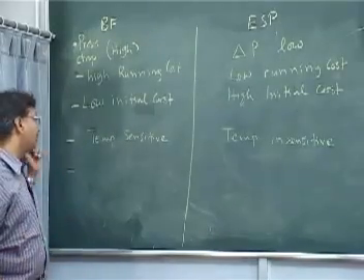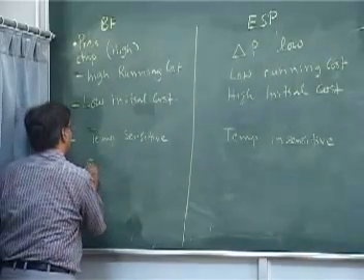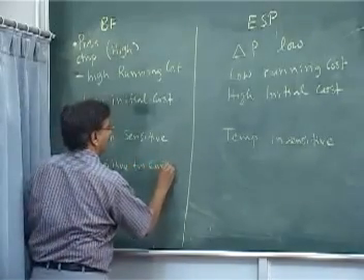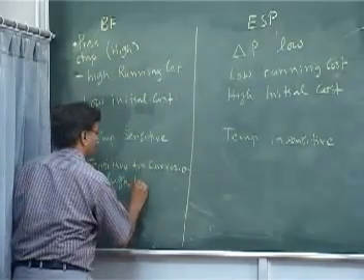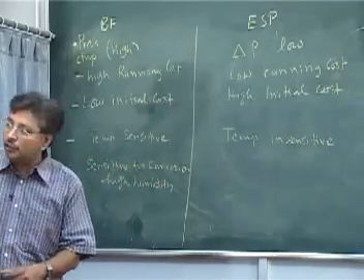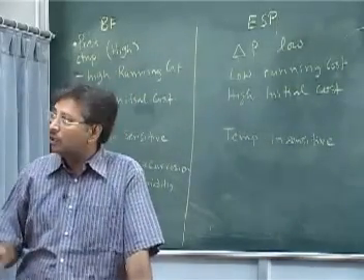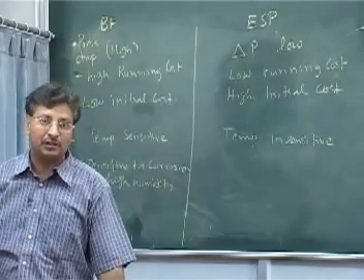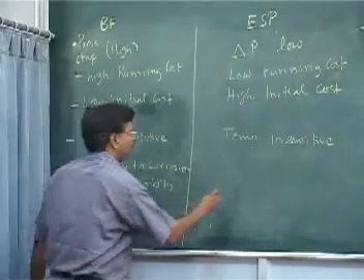What about the corrosive things? If you have corrosive gases or high humidity, the bag filter is sensitive, because if you are not maintaining the temperature, the humidity, water is always there in the combustion process, right? Flue gas will contain lots of water. If the temperature is low, that water itself will sit onto your fabric filter or make it non-operational. So it is sensitive to corrosion and high humidity. For the ESP, not such a problem.